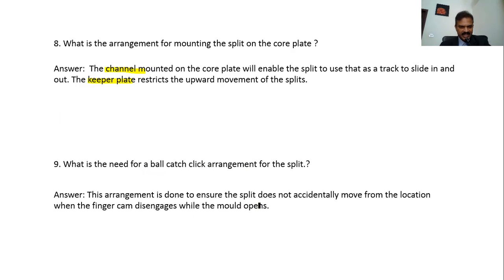If it is accidentally moved away, when the finger cam comes back, it won't find the hole to engage with. So definitely it's going to sit on solid steel and break. So in order to ensure that it remains at the same parking spot, we put a springy ball, which is the ball catch mechanism, which will go and click in the dimple provided under the slide.